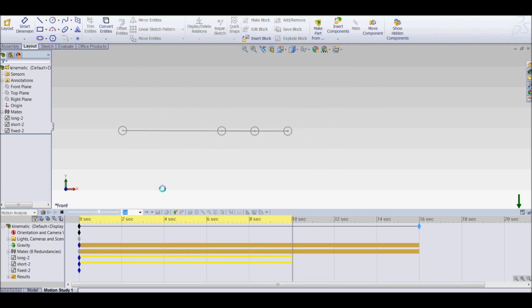So you can see by decreasing the integration step size and increasing the frame rate for the video capture, we've made the model nice and smooth with gravity driving the system.